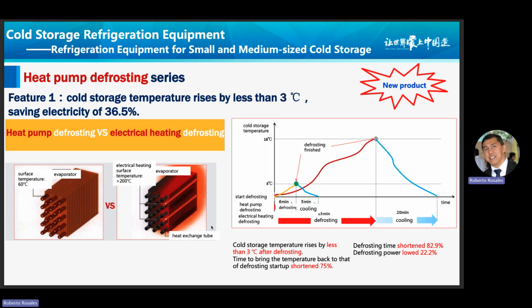Cold storage temperature rises by less than 3 degrees C after defrosting. Time to bring the temperature back to that of defrosting startup is shortened by 75%. Defrosting time is shortened by 82.9% and defrosting power is lowered by 22.2%.